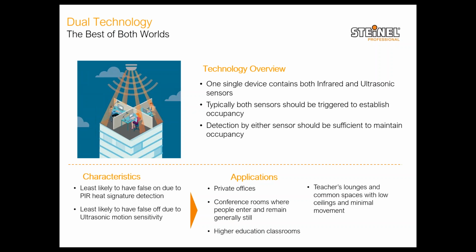We actually did have a question about dual tech as it relates to ultrasonic. This person uses dual tech for cubicles, but that's not listed on the applications. That's their standard, but you're suggesting ultrasonic. Why? Because in cubicles, 95% of the time, you're really using the ultrasonic part of the technology.